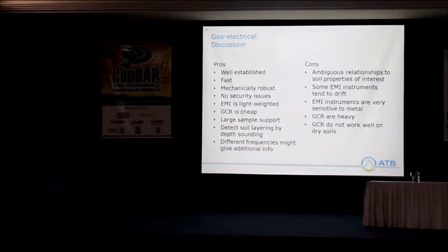However, relationships to soil properties are ambiguous, so you don't know exactly what you're measuring. Some EMI sensors tend to drift, and they are very sensitive to metal and sometimes also to temperature changes. Unfortunately, the resistivity sensors are quite heavy and they do not work on dry soils.